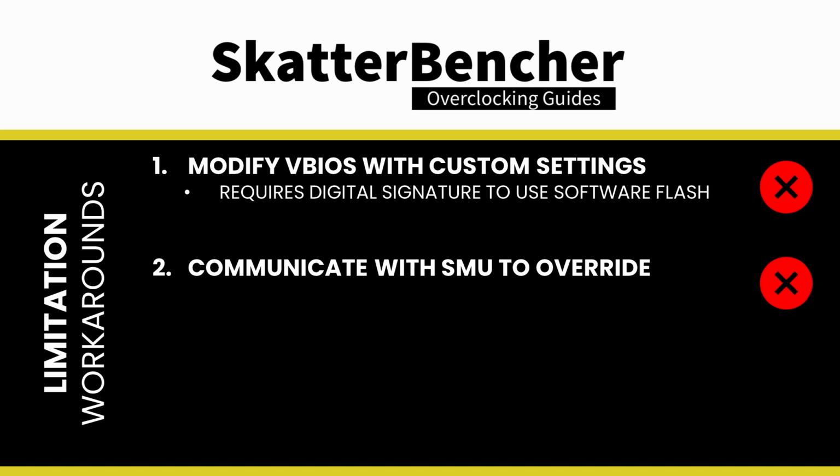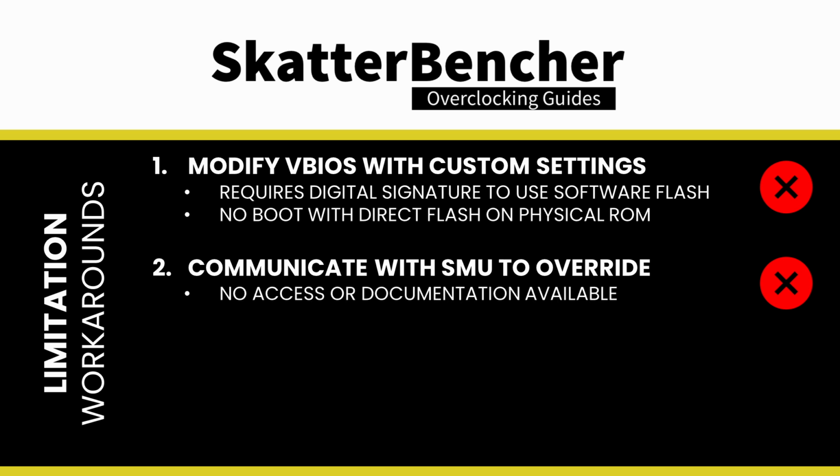Software VBIOS flashing tools will simply reject a VBIOS that doesn't have a valid signature. Modifying a VBIOS and flashing it onto the graphics card with a physical ROM flasher still gets the VBIOS onto the card, however, the card will simply not boot up. Communication with the SMU is very complicated, and unless AMD provides direct access, it's simply not possible.